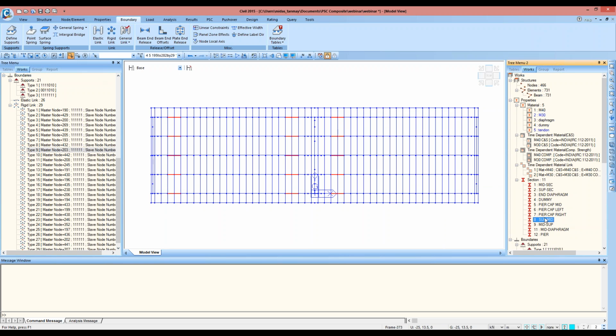Okay, and then support to mid. So these sections here should be mid to support. So I'll unselect these two and mid to support, drag and drop. So now support to mid sections and mid to support sections both have been created here.